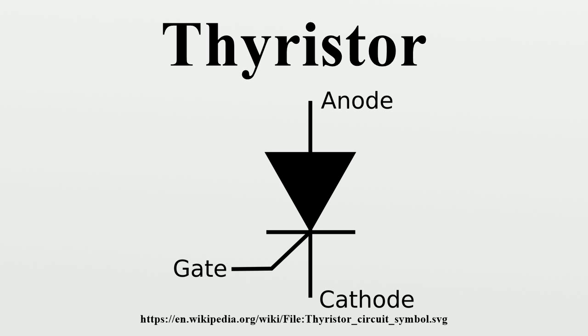Light-triggered thyristors are available with inbuilt overvoltage protection, which triggers the thyristor when the forward voltage across it becomes too high. They have also been made with inbuilt forward recovery protection, but not commercially. Despite the simplification they can bring to the electronics of an HVDC valve, light-triggered thyristors may still require some simple monitoring electronics and are only available from a few manufacturers. Two common photothyristors include the light-activated SCR and the light-activated TRIAC.